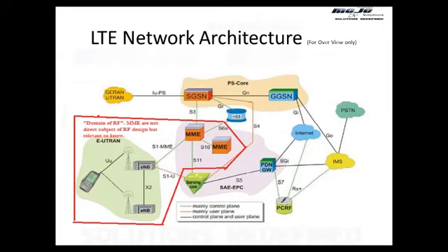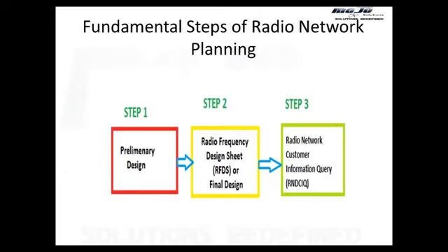That is one of the most basic reasons we see the progression: we were using AMPS, then GSM, then UMTS, and now LTE, and we are already talking about LTE-Advanced, because the technology is progressing and more spectrally efficient technologies are being adopted. So far LTE is considered the most spectrally efficient technology, which means, in simple words, it can deliver the highest data throughput to the end user.